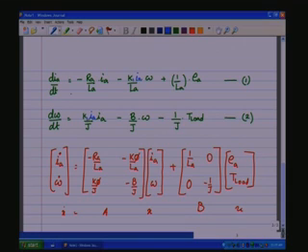So, we do not put it in the standard matrix form, because there is now state multiplication: I_A into omega, I_A into I_A, this is I_A squared. This is a non-linear system. Therefore, we just leave it as a differential equation system. So, that would become a non-linear system, but still that would give you the entire dynamic model of the DC